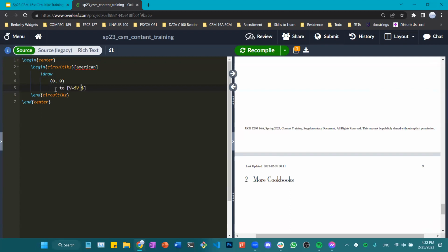And then that was the voltage source. So I'm going to put V equals Vs here. And since the positive sign should start at the starting coordinate, I'm going to press a comma, invert, so that I can invert my voltage sign. Okay, and then relative positioning. Okay, let's see what this does.